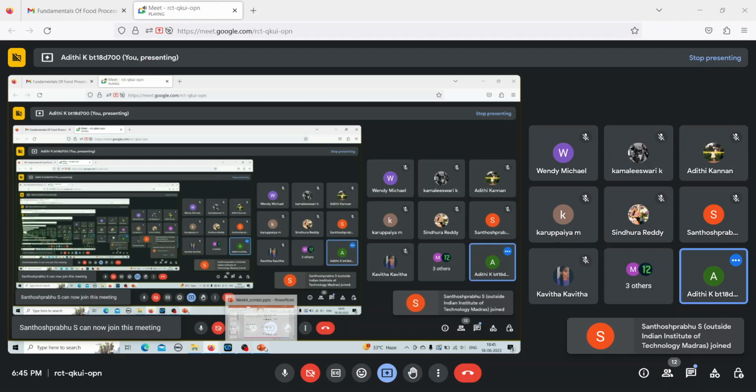So we already have XP here, that is the total amount of solids in the product stream, which is 0.37. We know XF, the total solids present in the feed, which is 0.12. But unlike the previous questions, we do not know the mass flow rate of the feed. What is given here is the rated evaporation capacity, which is 242 kg per hour of water. This water corresponds to nothing but the vapor that we get after the evaporation process.